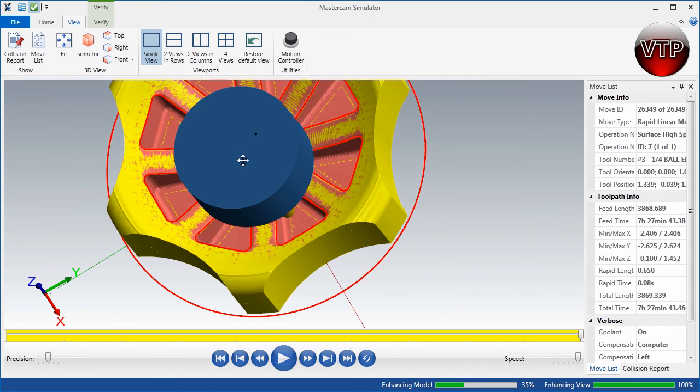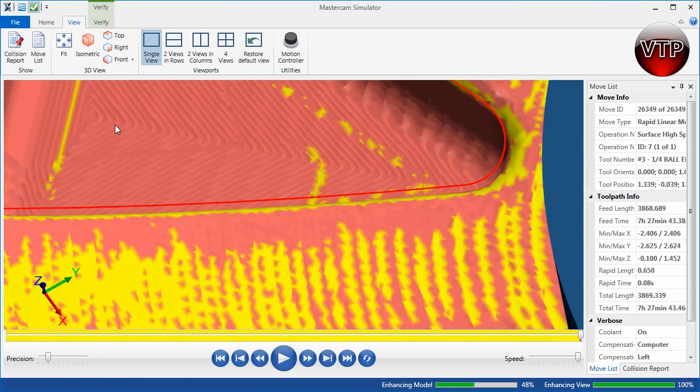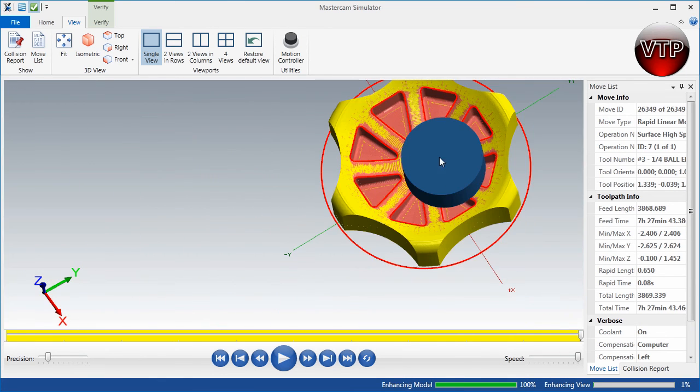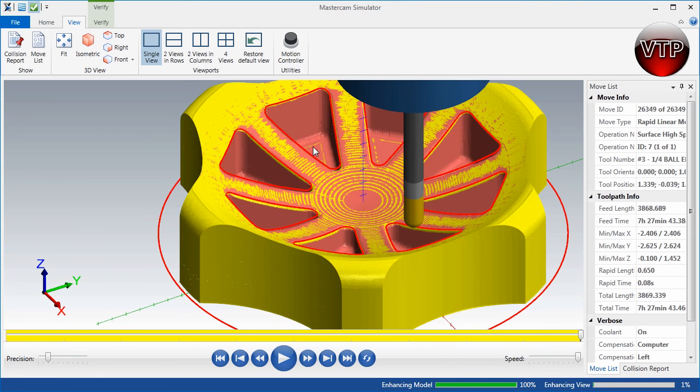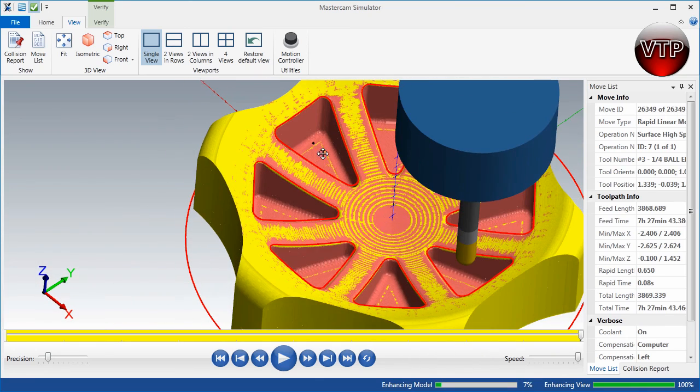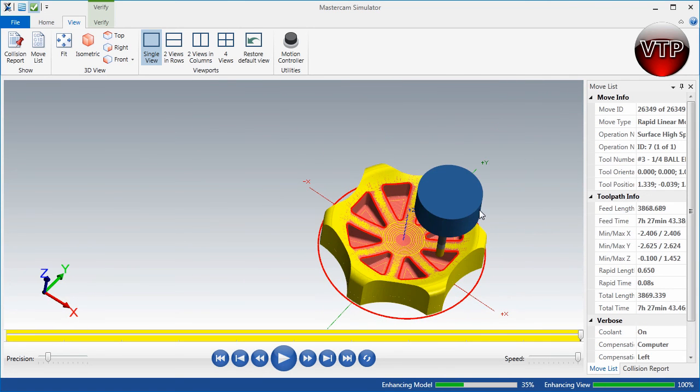Now, obviously, you can actually go back in because some of my pockets, as I see, are not the smoothest finish. So that's something you can go back in and play around with the values and the step overs, especially to machine a very flat surface at the bottom over here. Or you can even, for the pockets, go first in with an end mill before going back in with a ball end mill to machine the corners of the part. But there you go, all finished. This concludes exercise number 4.